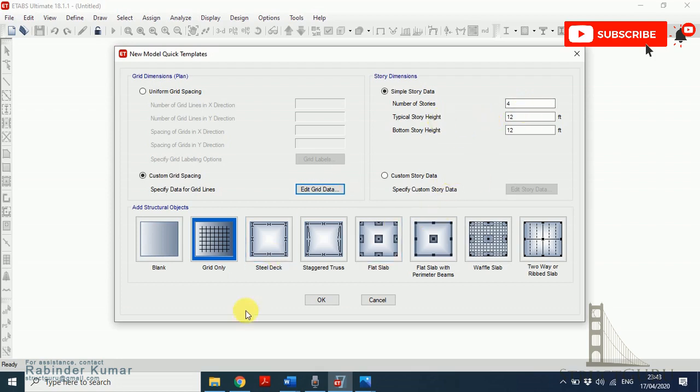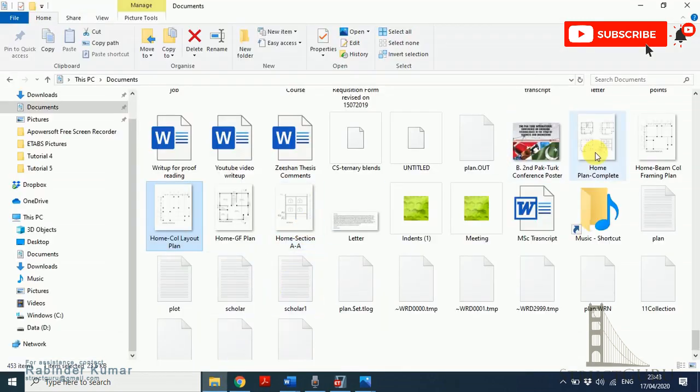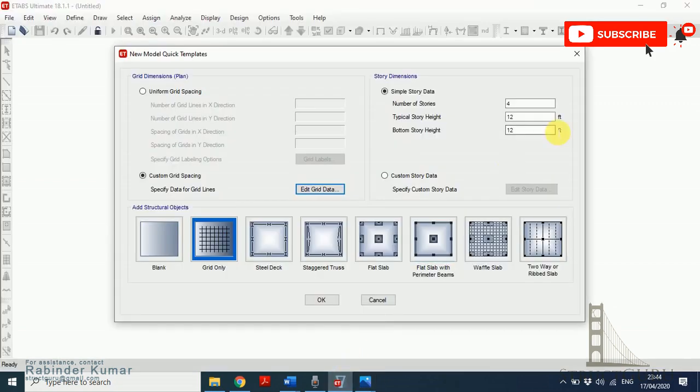All this data will be given from the sectional plan, which is given to us by an architect. So let me open a sectional plan. As you can see, from foundation level to plinth level it is 8 feet, from plinth level to first floor level 12 feet, and from first floor level to roof level again 12 feet. So we have 3 stories: first story, second story and third story. So let's put this data into the ETABS model.